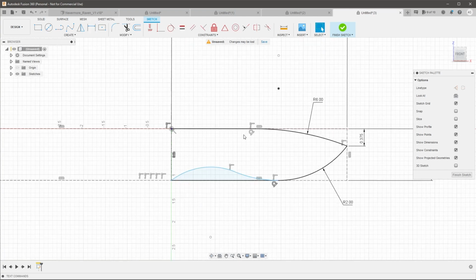But whenever you start to get into complicated S curves, let's say, where it swoops back up, back down, etc., that's usually a pretty good opportunity to evaluate whether or not you want to use a spline or not. And whether, depending on the complexity of the shape, maybe a spline is the right tool, or maybe you want to invest the time to fully constrain this? So thankfully, this one is actually fairly easy to constrain.